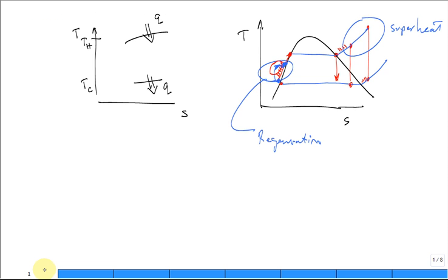So let's talk about first superheating, and then also I should back up. I should also say one of the strategies if you want to bring in a lot of heat is not only to superheat it tremendously. Often there's a metallurgical consideration, a maximum temperature limit. So you'll superheat it to the maximum that you can, and then expand it to an intermediate pressure.